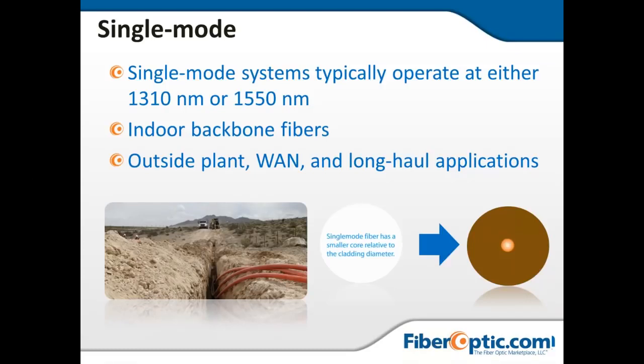Single mode, to kind of represent the fact that single mode is going to be their long haul applications. Seeing much more single mode applications in the premise environments as well, between buildings and even on campus now. For a long time it wasn't the case just because the cost of single mode was so much more expensive. The LEDs that we use to launch into a multimode fiber were a lot less expensive than the single mode transmitters and receivers. So there was some advantage and cost savings on the short haul to use multimode.